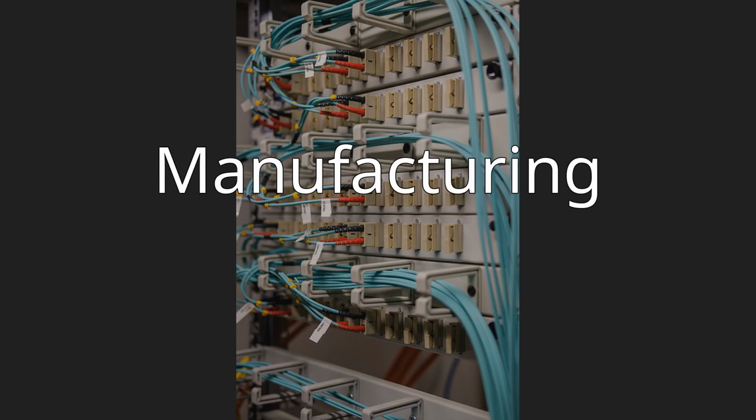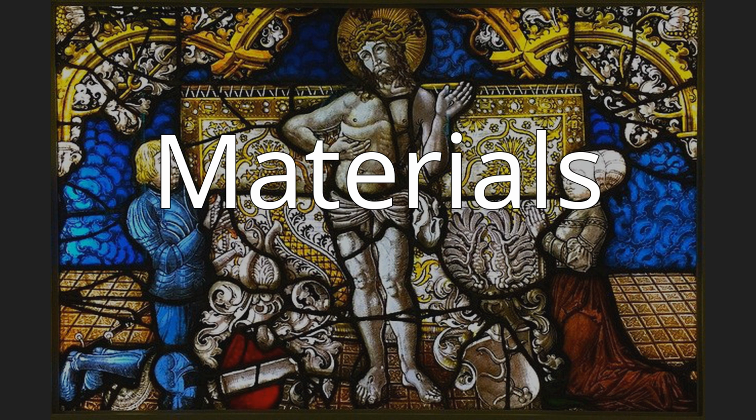Manufacturing. Materials. Glass optical fibers are almost always made from silica, but some other materials, such as fluorozirconate, fluoroaluminate, and chalcogenide glasses as well as crystalline materials like sapphire, are used for longer wavelength infrared or other specialized applications. Silica and fluoride glasses usually have refractive indices of about 1.5, but some materials such as the chalcogenides can have indices as high as 3. Typically, the index difference between core and cladding is less than 1%.